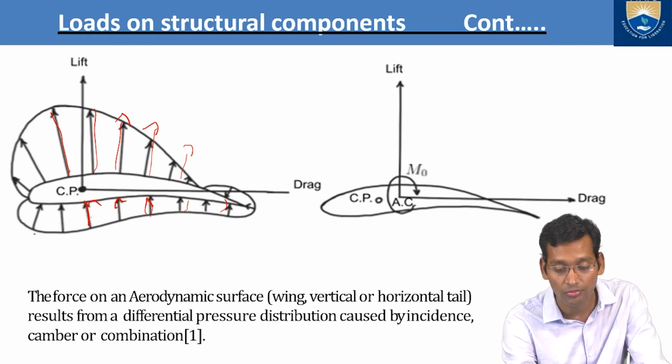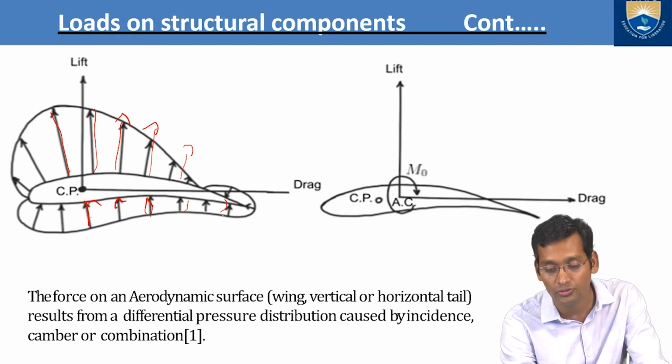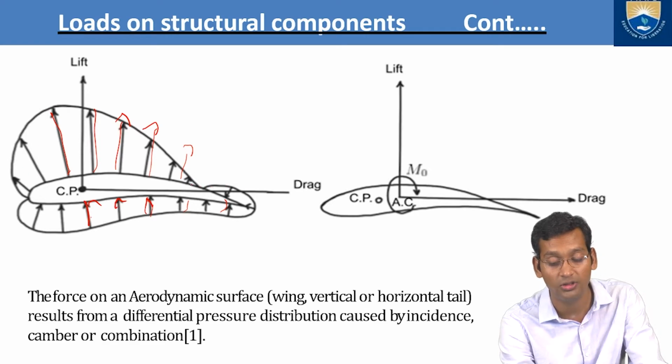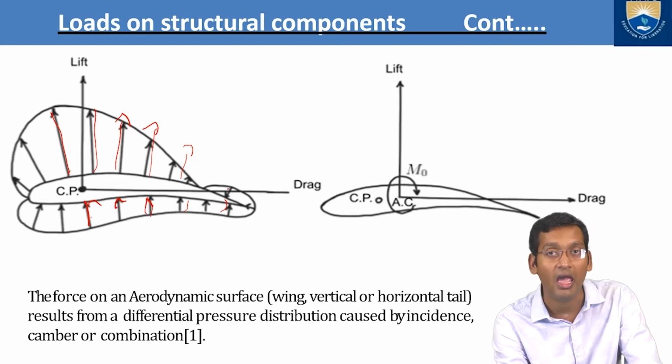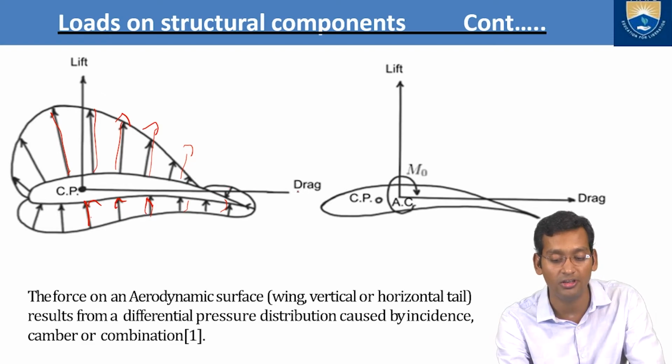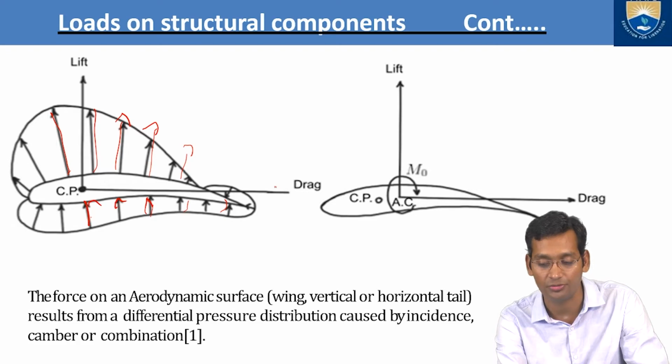Now see how drag is produced. This force is the pressure difference, and it comes up to this part here, not over this one. The bottom part has the higher pressure, so higher pressure is generated here, or because of the separation of flow. Here drag is produced, and that's why drag always acts opposite to the motion, on the backward side.